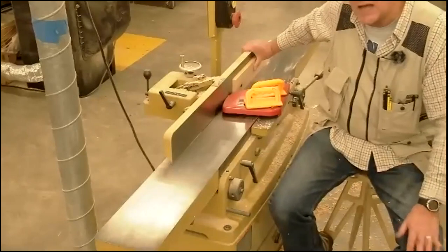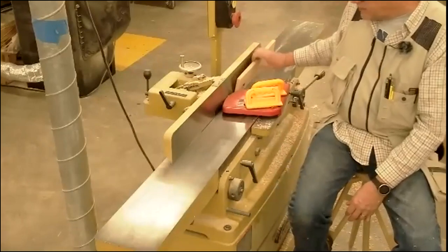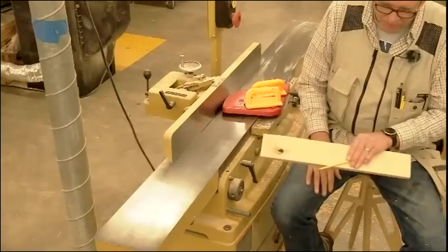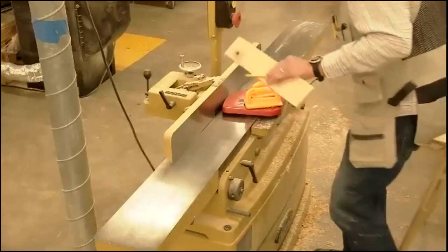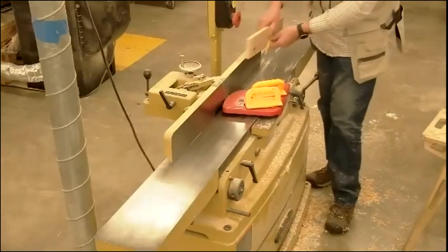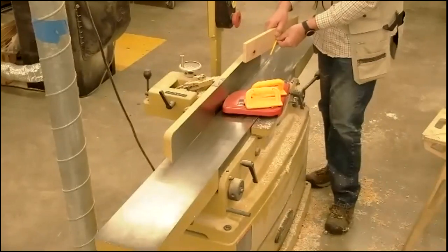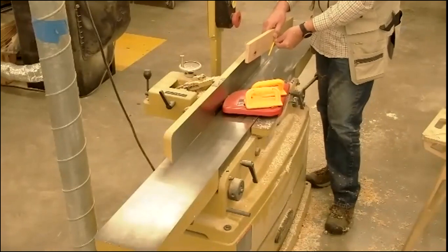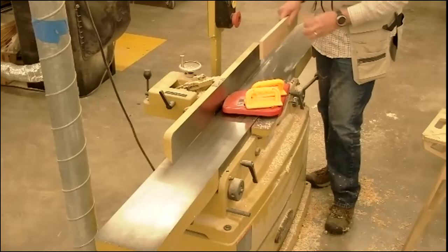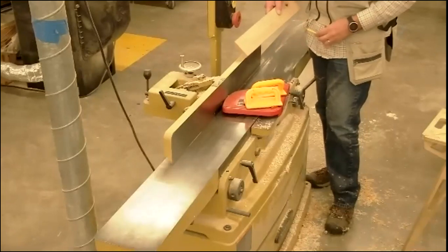The nice thing about having both faces flat and parallel to each other is this. If you have a lot of grain diving out in that direction, okay, and you only have one face on the board jointed, you didn't plane the other face, all right? If I put the board like this, I'm going to be going against the grain. I want to go with the grain, okay? So in order to do that, I have to flip the board end for end, okay? That's the only choice I have to try and go with the grain. And it's entirely possible that on the other edge of the board, it's coming out in the same direction.